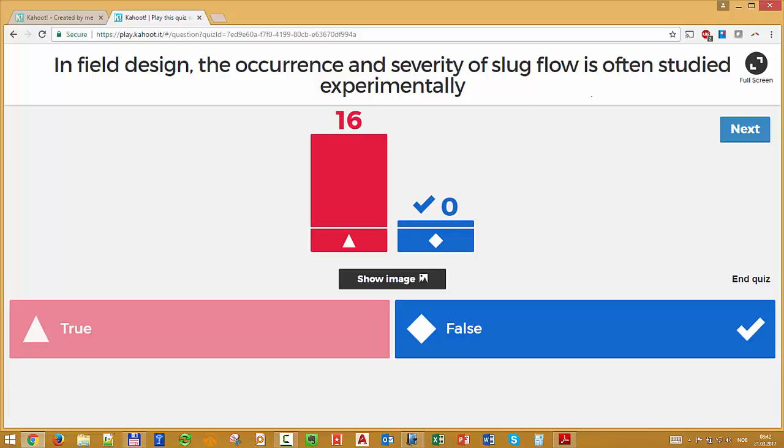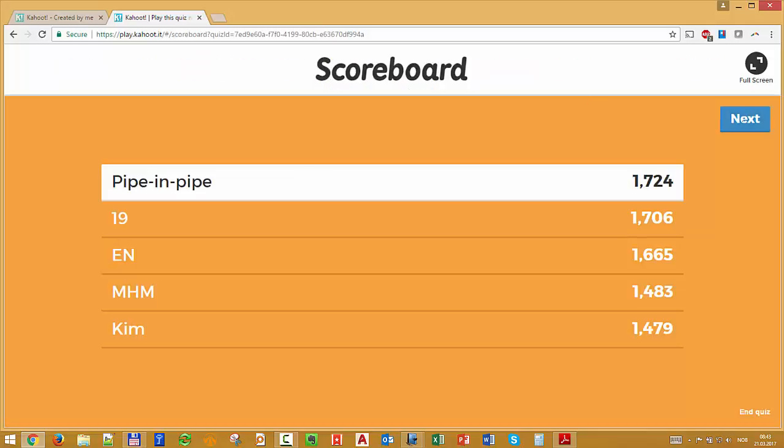If we see that we have a very challenging situation, like long transportation distances, potential problems of liquid accumulation, this riser configuration, and we think that the models are not predicting very well, then in that case we might commission experiments like this exercise 3. Oh no, it was exercise 1, was it? That you have this issue that the flow assurance expert said this is not good for our particular case. You might commission experimental studies, but this is not very common, because they are expensive. They cost money, they have to be done at large scale, and it's only if we have a very challenging situation that we use it. Okay, we didn't change much.